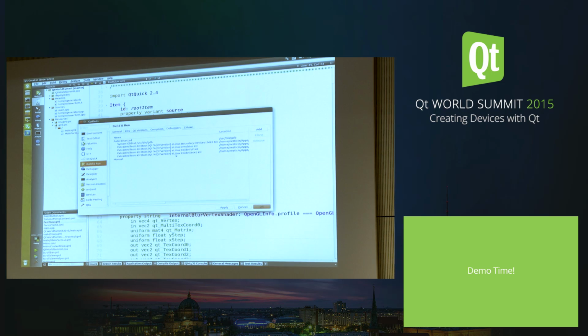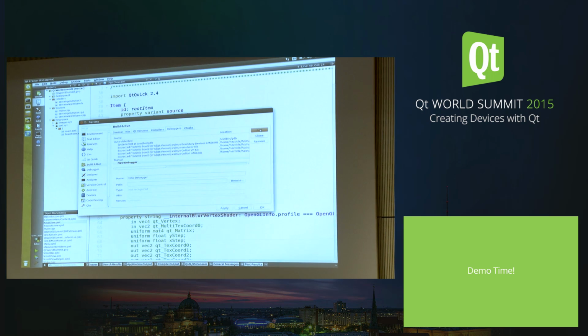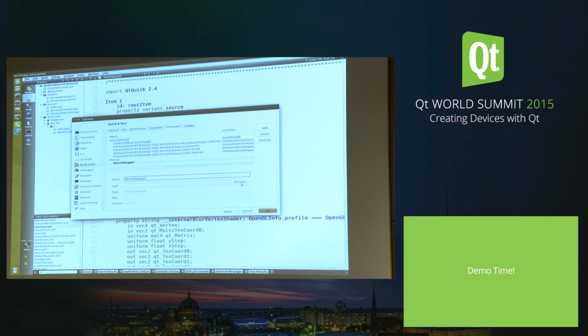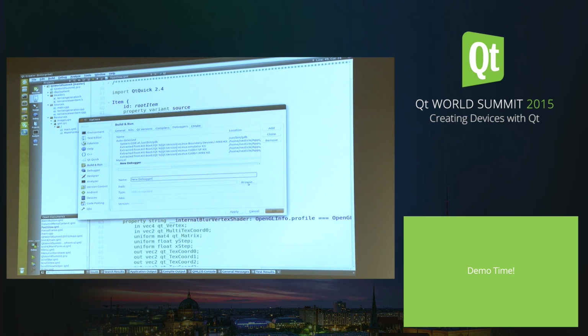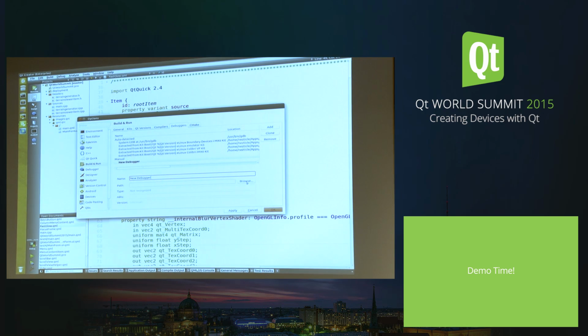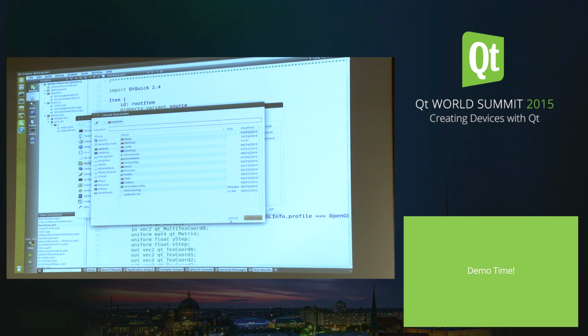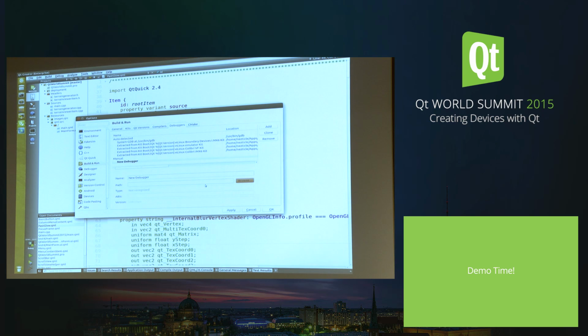So in the case of the debugger, I would hit Add, and then just give it a random name. So, IMX6 debugger. And then if you have a version of GDB that supports talking to remote ARM things, you just find that binary. And this is going to be generally in your toolchain folder if you've built GCC in the same places. So your host tools, toolchains.